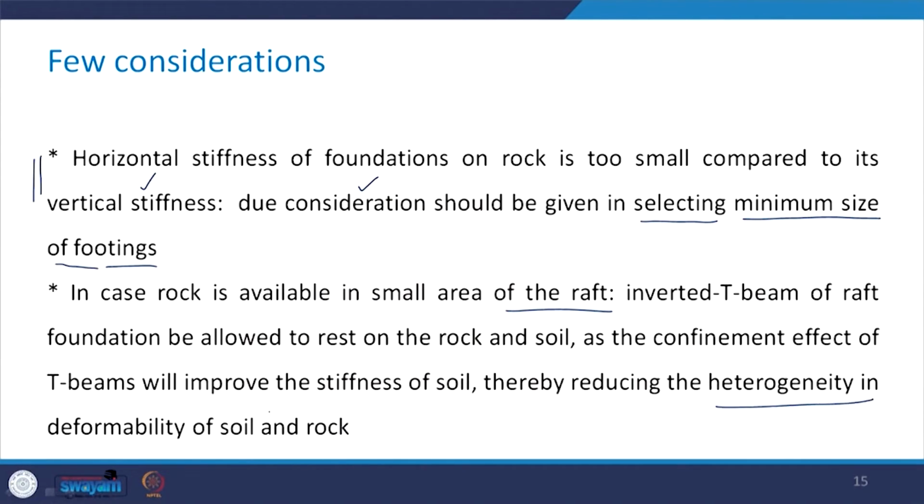So, since the deformability of the rock and the soil are different, the raft may experience differential settlement, and this is not desirable because this will cause cracks in the rock. So, therefore, to reduce the heterogeneity in the deformability of rock and soil, this should be adopted.